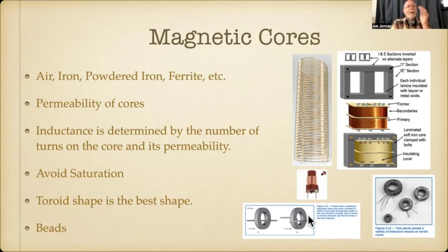Yeah, you can buy a satisfactory size or bigger. So you can use a larger core, and then there will be less chance of saturation. True, and it'll cost you more money. You would not want to select a smaller core because it would become saturated before you got to where you wanted to be. Correct. Thank you. Answer your question.